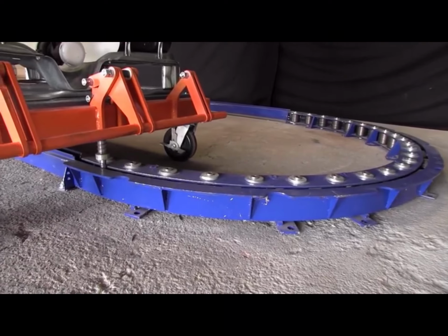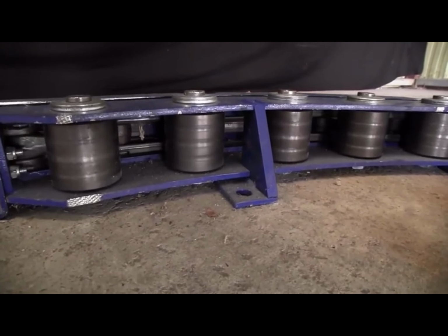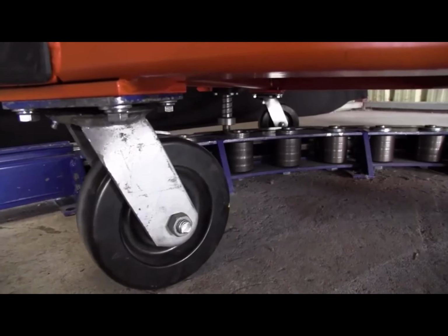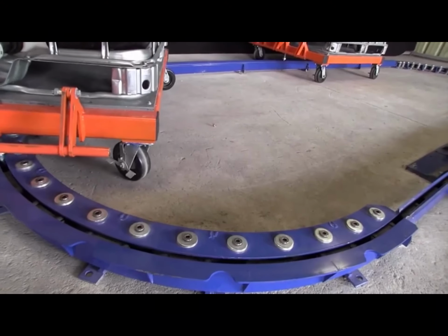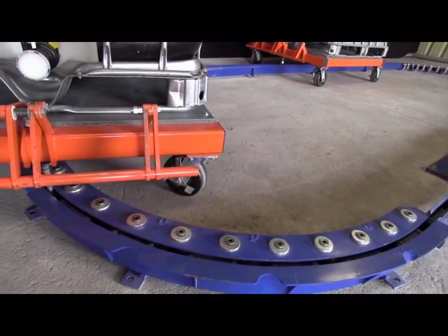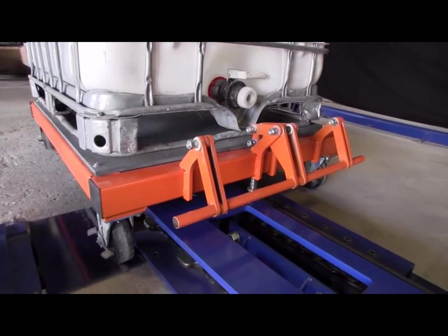Thirdly is the curve load capacity. The PackTrack 100 utilizes heavy-duty, free-turning roller capstans to guide the chain and its load around any curve. This removes the chance of heavy wear on the inside of an enclosed track and also accommodates the movement of a heavy load through any turn with far less power required from the drive unit.